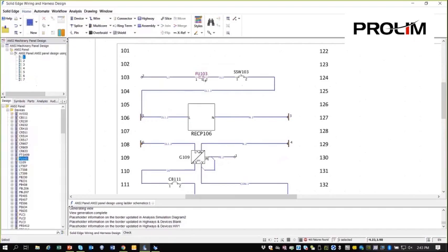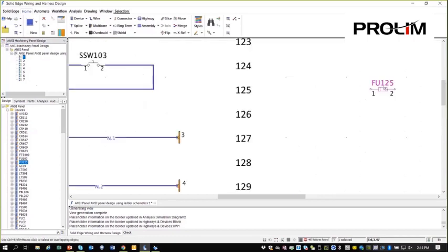So this fuse, for example, if I moved it to a different position, we want this graphic to be smart enough to rename that part. And that's what you see happens here with the fuse 103. I can take the same, move it over here, Control V, and when I put that down, I get the proper naming convention that I'm looking for in the ladder diagrams.